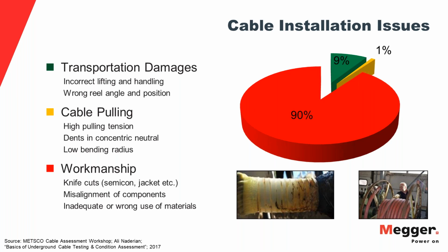Then you have some issues with cable pulling, which always happens, and transportation issues, including, by the way, I didn't write this here, storage issues. Sometimes when you see various utility yards, you can immediately tell if certain cables will cause you problems down the road, because there's a specific way of storing the cable drums. If you don't do it that way, let's say you put them upside down or flip them over the wrong way, that will cause sooner or later at least some mechanical deformation of the cable drums.